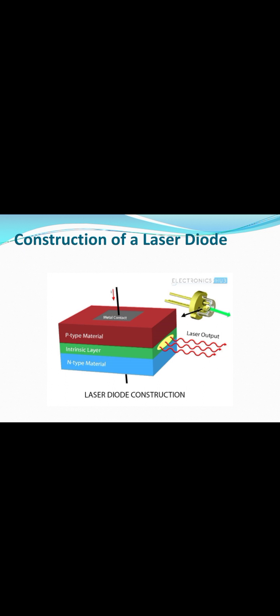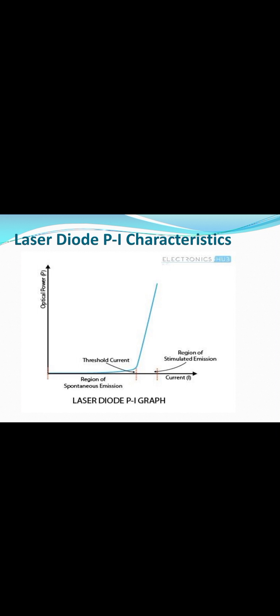It is necessary to know some properties of semiconductor materials with regard to p-n junctions. A semiconductor crystal with no impurities or lattice defects is said to be an intrinsic semiconductor layer. This is the energy band, and these are the parts for the construction of laser diodes. Now the main parts of the laser diode are a metal contact, p-type and n-type semiconductors using the intrinsic semiconductor between them, and lastly the other metal contact.